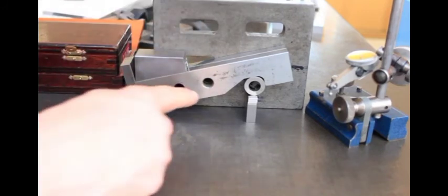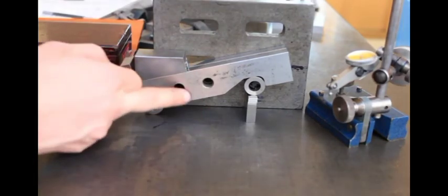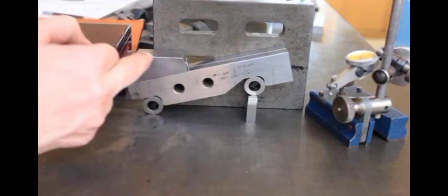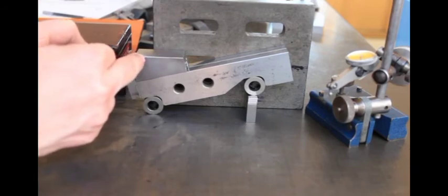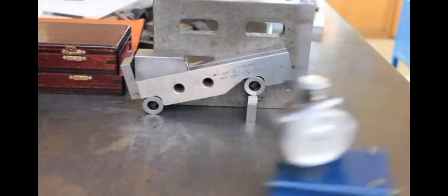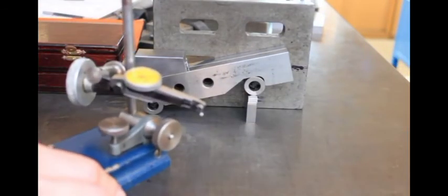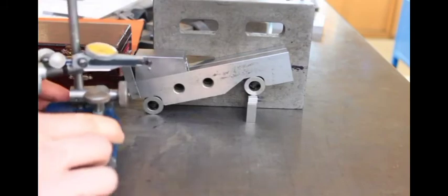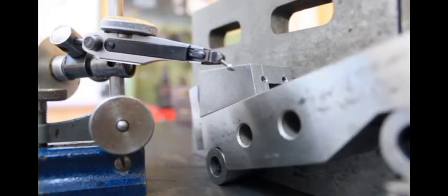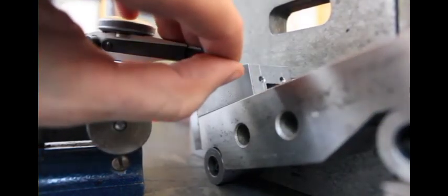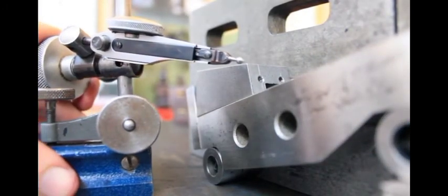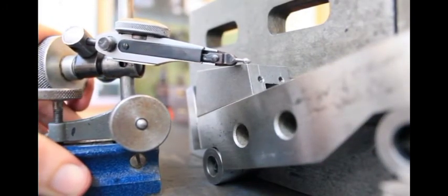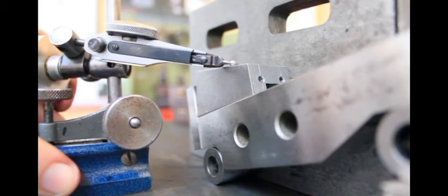What we'll do is run a dial test indicator across that top surface so that we can check whether it's running out or not. If it doesn't run out, we'll get a reading of 0. So we need to line up our DTI so that the finger is roughly at an angle of 20 degrees or so when we first start. That way, when it makes contact with the block, it's near enough horizontal, and that's going to reduce sine error. Then we can move it back and forth.